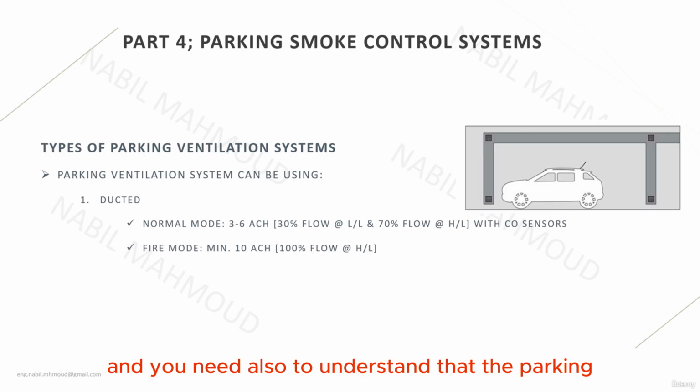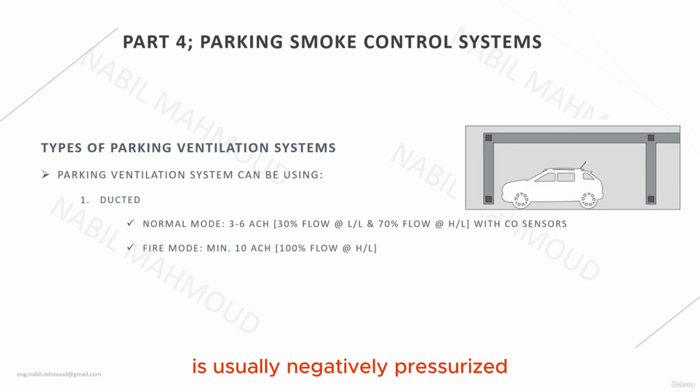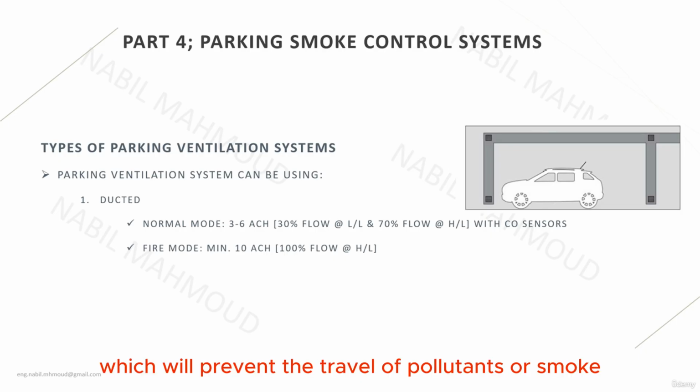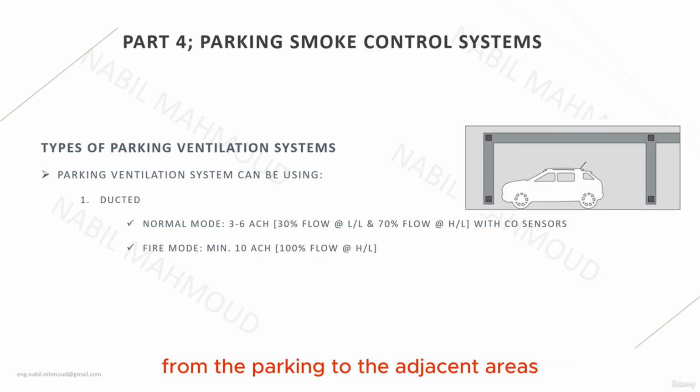And you also need to understand that the parking is usually negatively pressurized, by an approximate value of 85 up to 90%, which means that the extract will be more than the supply with this ratio, or the supply will be 85% up to 90% of the extract value. So the supply will be less than the extract, and this will cause the parking to be negatively pressurized, which will prevent exfiltration, or the travel of pollutants or smoke from the parking to the adjacent areas.